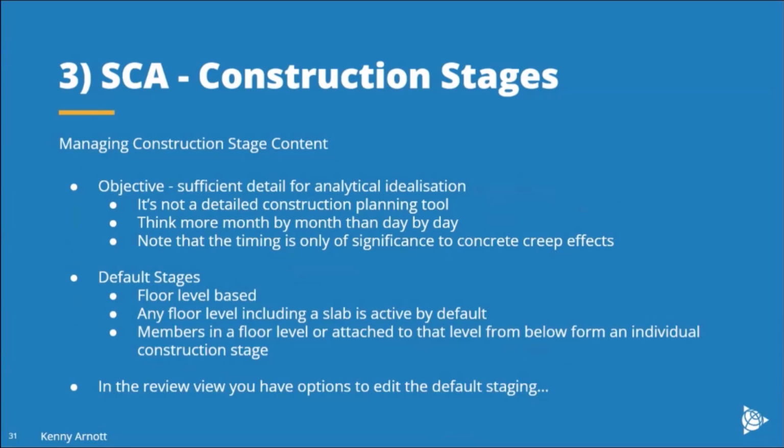So it's not a detailed construction planning tool. Try to think more month by month rather than day by day. And the timing of the stages, as again, we'll show you how you can set and edit that. But that only has significance to the concrete creep effects. If you didn't have concrete in the structure, the timing just wouldn't matter at all.